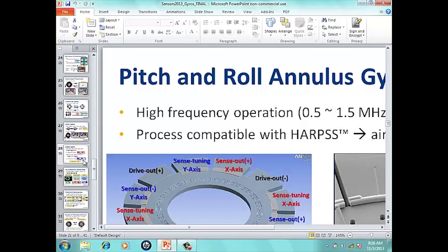Yeah, so you probably can get better resolution on an accelerometer, but I don't think the problems are too small. I think that for MEMS accelerometers, you end up having the same type of complication. But if you can come up with an integrated velocity sensor, then you get rid of one of those integration processes. But now the question is, how do you design a velocity sensor? Doppler effect, perhaps.